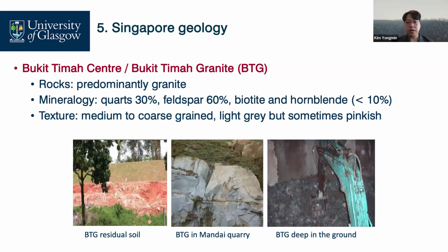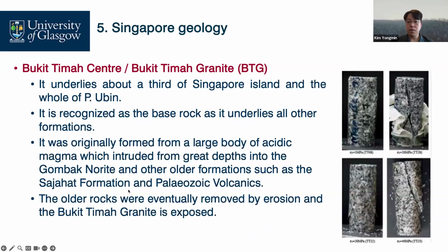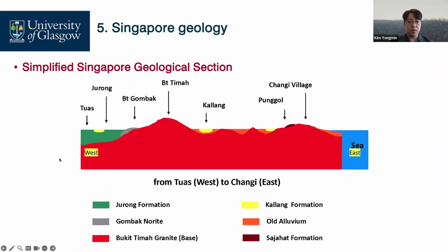So let's quickly take a look at the Bukit Timah Granite. It is predominantly granite and medium to coarse grain rocks. They show light gray, but sometimes pinkish. It underlies about a third of Singapore. It is recognized as the bedrock of Singapore because it also underlies all the other formations, looks like that. The red one is the Bukit Timah Granite.